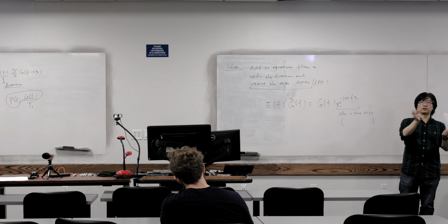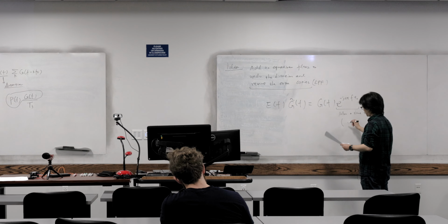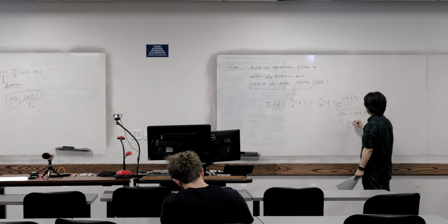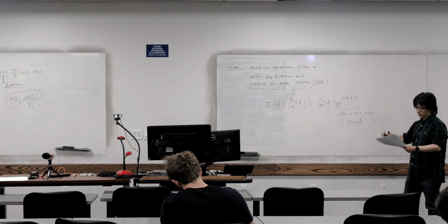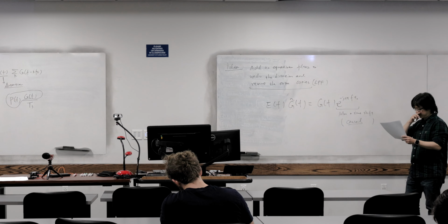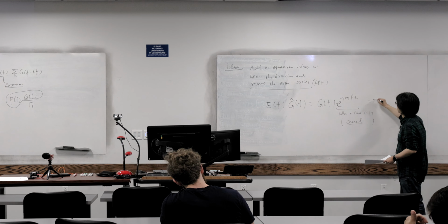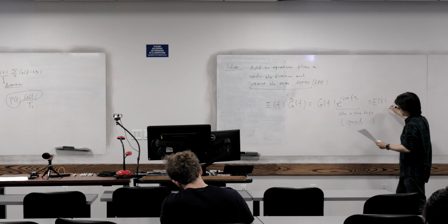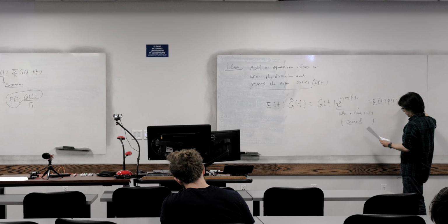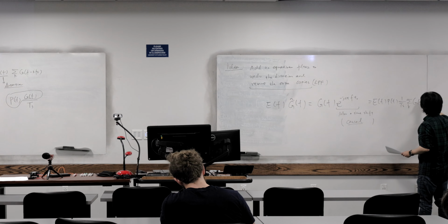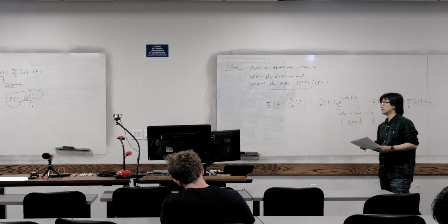We don't want anything below 0. So we can make it causal. Then we allow the time shift, so this is what we want. Again, this would be nothing but E(f) times P(f), times 1 over Ts, and then the summation over k of G(f minus k fs). So this is what we got.